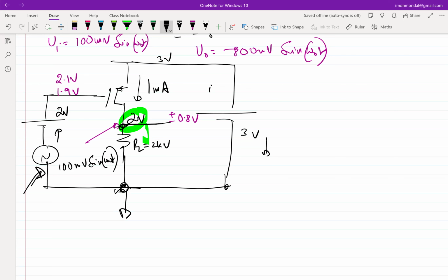Right. So you can apply a minus 0.5 volt battery, or minus 0.3 volt in this case. Minus 0.3 volt battery, and you're good. But there's another practical issue. Negative batteries are not very easy to get. You can flip, but you will see later on why I say that. Ultimately, it looks like for one transistor, you have used 3 batteries. And if you have 100 transistors in a network, would you use 300 batteries? That's not possible. So next time you will see that we have to derive all these battery voltages from one source, one battery. We'll do that later, but take that for the time.